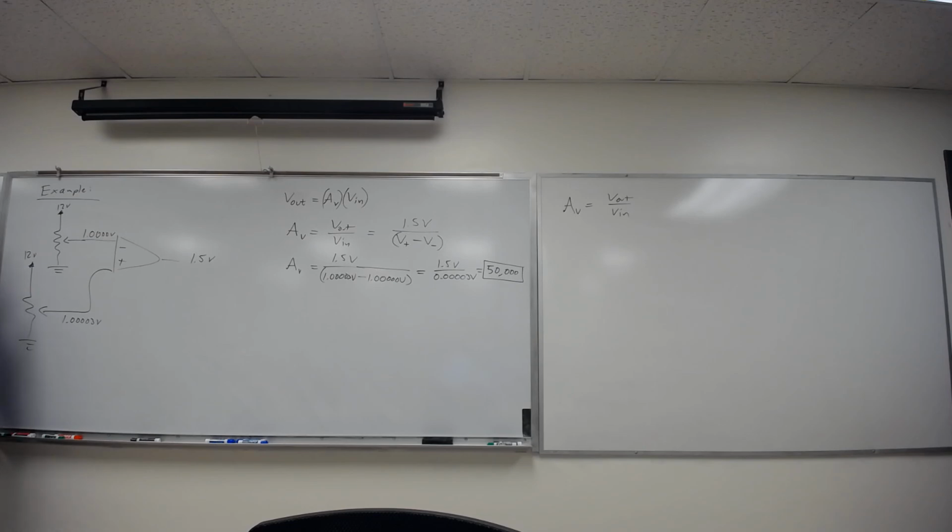This is a bit about how we could go build this in class, couldn't we? I just get a 12 volt supply, connect 12 volts to this, negative voltage over here. Use a couple of potentiometers, set these voltages, and then I'd probably just plug one in at a certain voltage, and then just set the other and turn it a little bit, and see. I should have a gain across the whole region.